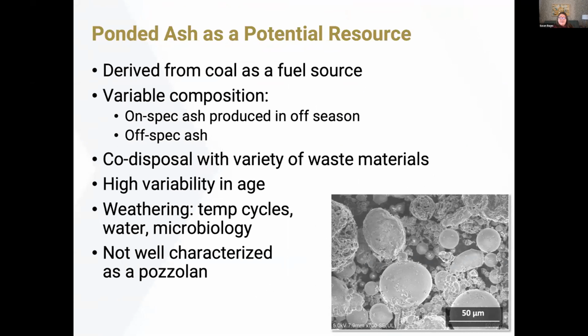Some ashes that are ponded were great fly ash, but it was produced in the off season. There was not enough construction going on to use this ash, so they disposed of it in a pond. Some ponded ashes are high organic content or off specification ashes. And usually these two are mixed together in the electricity plant's disposal ponds, so you can't separate them out. That is the other part of the problem.